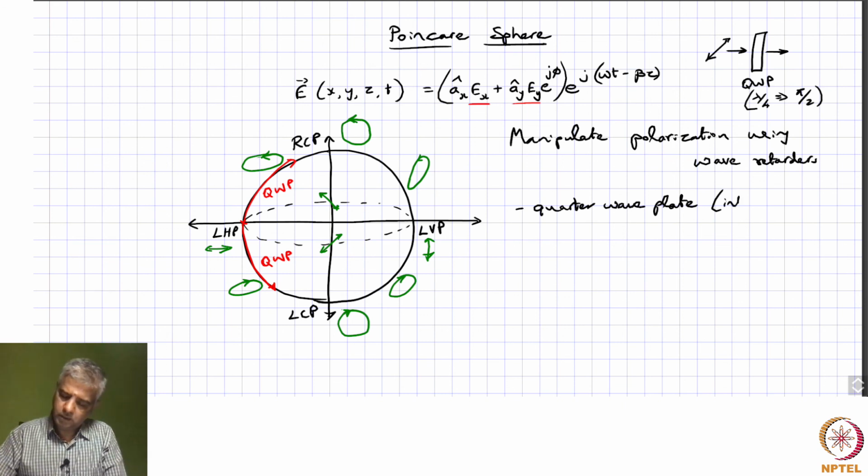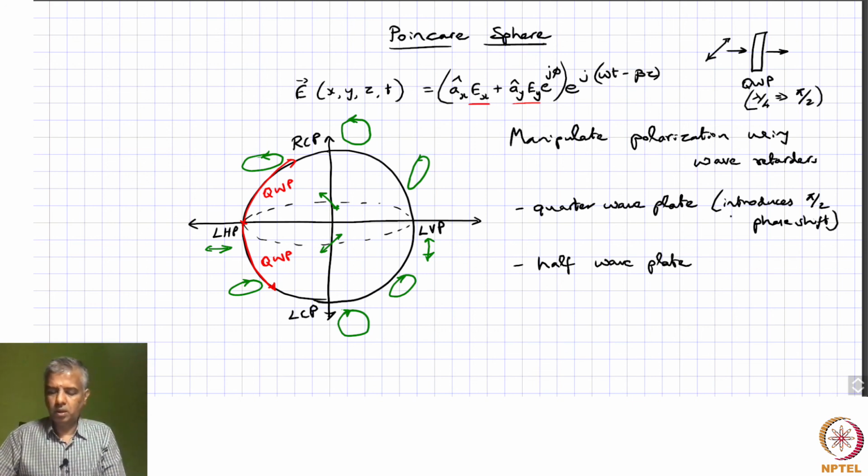So when you come back here and look at this, what this optical demodulator does is analyze the polarization state, and you know what you launched into your fiber at the transmitter. You usually put a polarizer here to ensure that you are launching a very specific polarization state, and then you analyze the polarization state at the output.